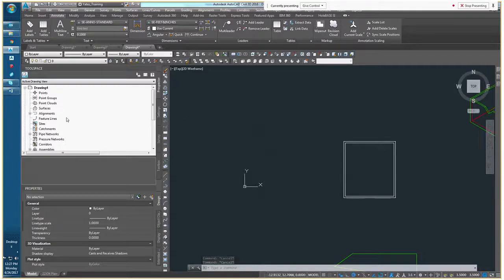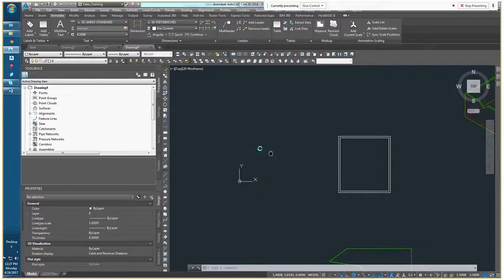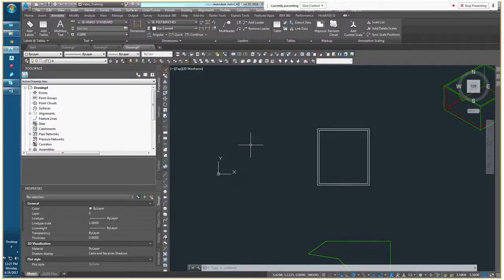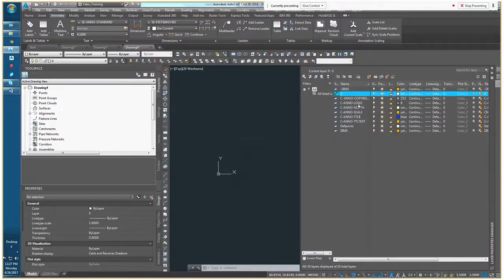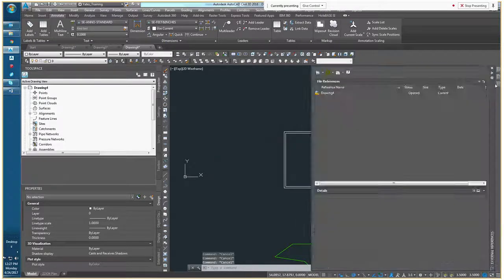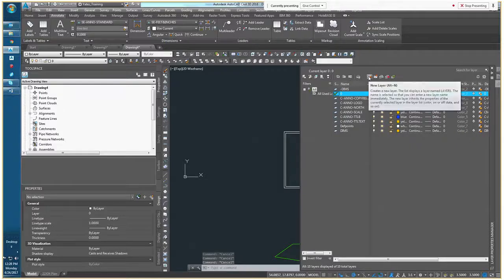But in general, we want most objects in our drawing to be on their own layer or on a shared layer with other similar objects. And it's pretty easy to do that. We're in the detailed DWG template, so we have a very short layer list. But what I'd like everybody to get in the habit of doing when they're working on projects is creating their own user layers, or before they start drawing something, selecting an already existing layer that makes sense. Now, when you're in the Civil 3D template and you're using surfaces and alignments and things like that, our template is set up to create their own individual layers for each surface and each other Civil 3D object. And that allows us to turn things on and off within the drawings as necessary.